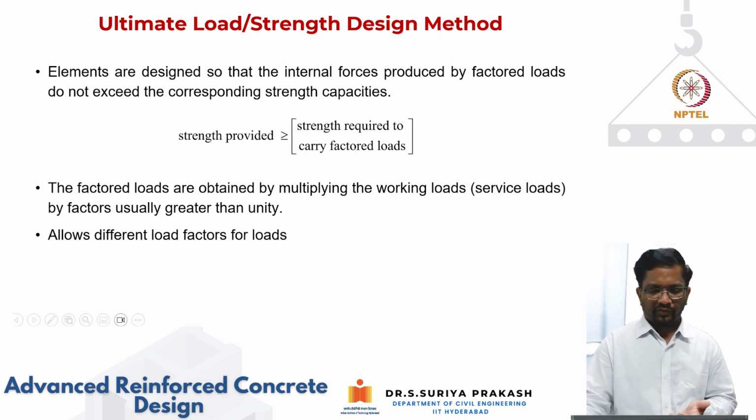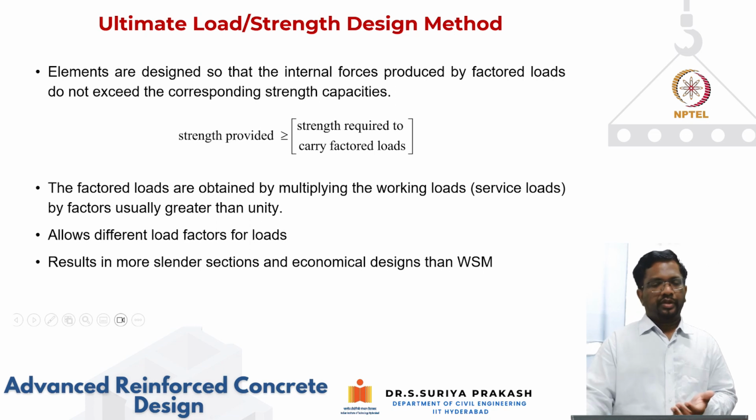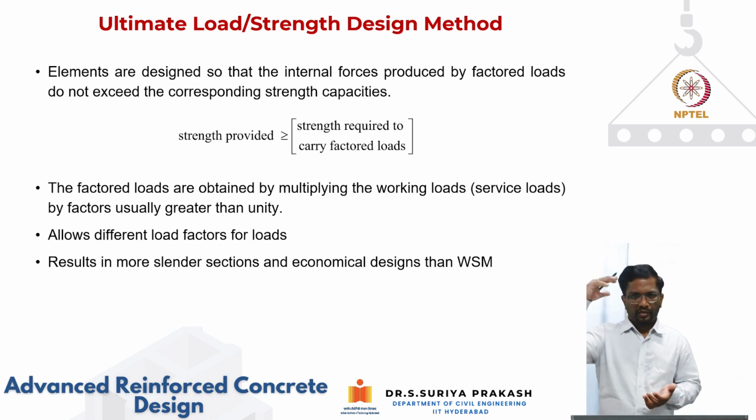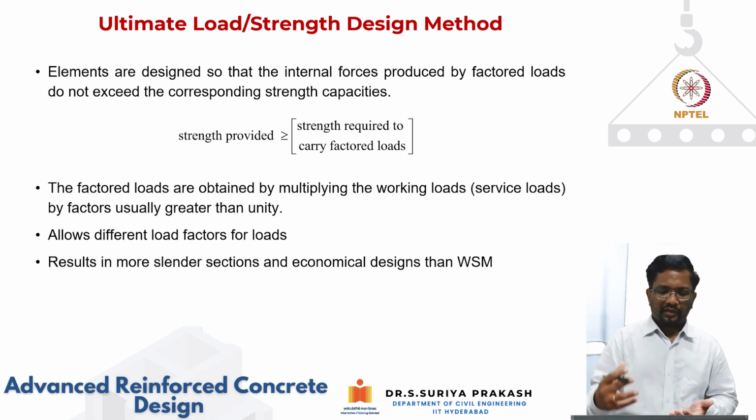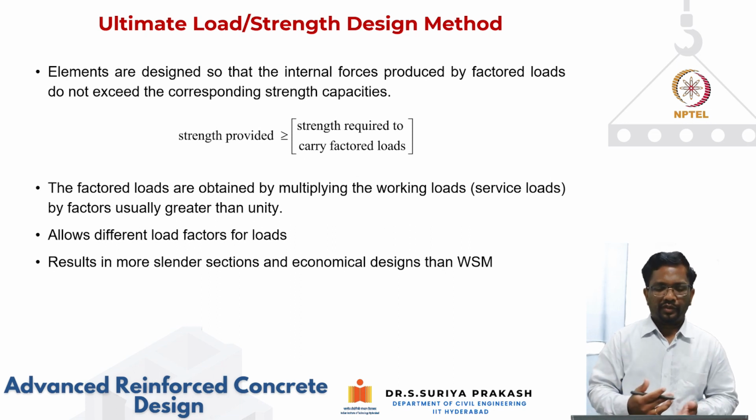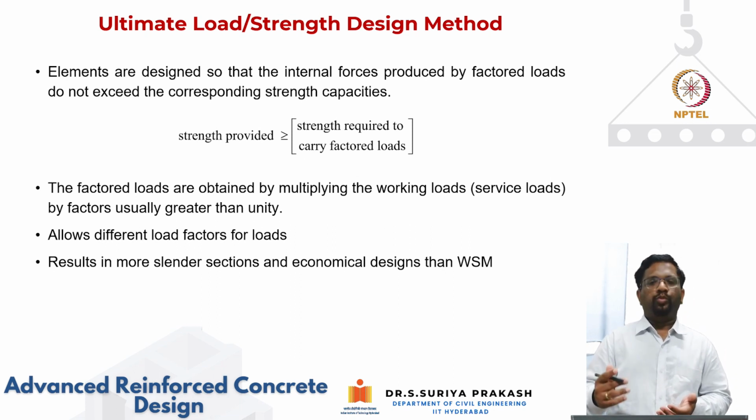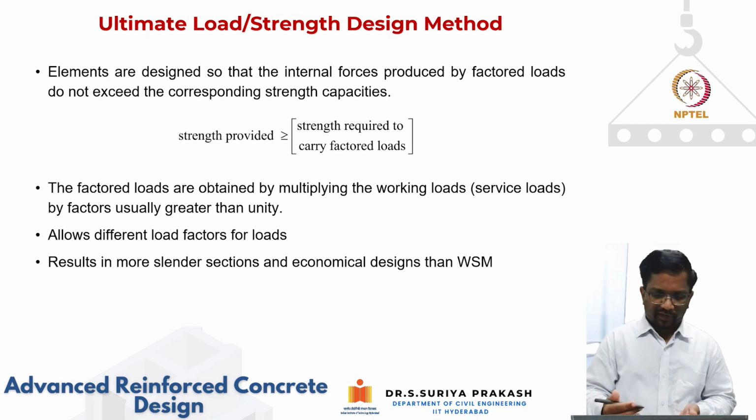So this method allows for different load factors for load, and because you're dealing with maximum strength of the material in these checks, you usually end up with more slender sections and more economical designs than working stress method.